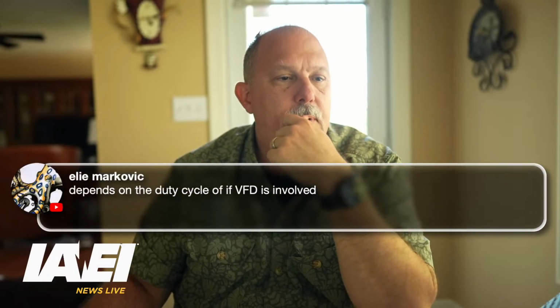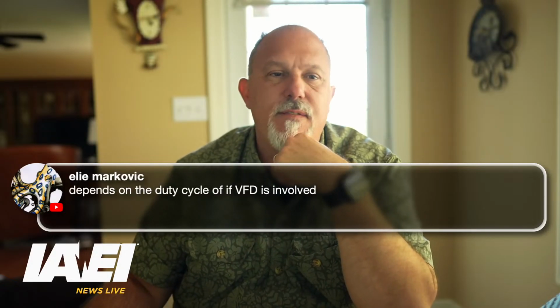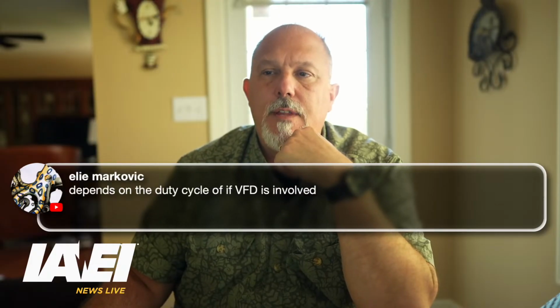Now, somebody brought up, Steve, there's Eli. Was it Eli? Yeah, Eli brought up this. Depends on the duty cycle if a VFD is involved. That's right. So now we have the other aspect that you have something in between the branch circuit overcurrent device and the motor.